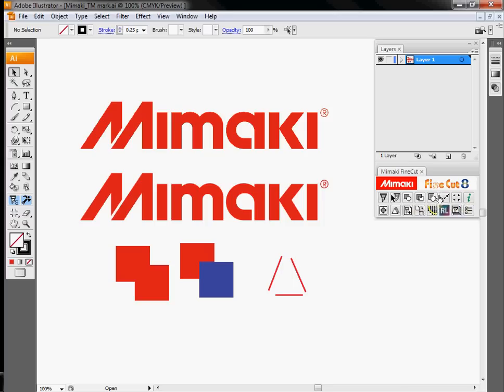The remainder of the icons on here are really more about path and object manipulation. So we'll start up here at the top and kind of go over to the right. This first one, basically recognized stroke, weight, and overlap, is for combining 2 objects. So if I go through and cut this right now, it's going to attempt to cut out both of these squares. So I'm going to have some lines going through here that I don't necessarily want the knife going through. By hitting this button, it'll basically combine these into a solid shape. So if I had a company logo that was vectorized, that had some extra lines in here, I can get rid of any excess lines that are in there.